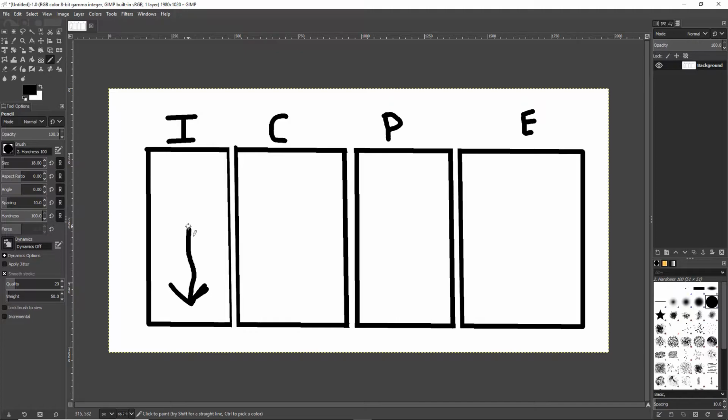And then guys, this is the easiest way to remember it. We always start on intake when we explain this, and if you can remember that intake goes down because I'm creating a vacuum to pull air and fuel in, then you know what the rest are. If I'm already down, I can't go down again, right? So therefore I must go up, and if I'm already up, then which way am I going? Right, so this is pretty simple. This is the easiest way to remember this. Please take note of this, guys. I am going to make you draw this for me, this exact same way when we meet in class. This is super important that you understand this.